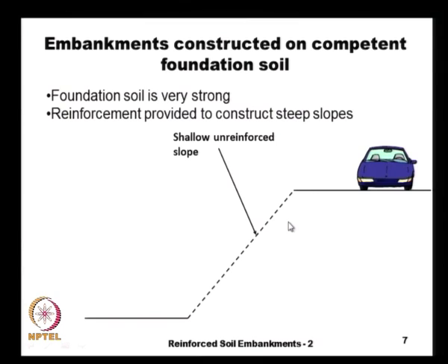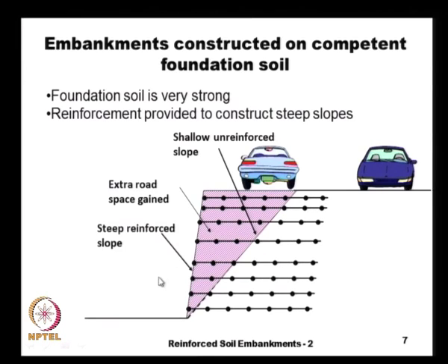And continuing our discussion, many times when we have road embankments and other things in the city areas, we may be faced with the requirement that we need to construct very steep slopes, and one example as we had seen earlier is like this. Let us say that we want to widen this road, and the only way to widen this is either to make this slope a steep slope, so that we get extra space, or procure more land and widen the construction area.